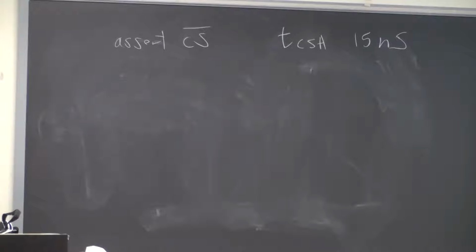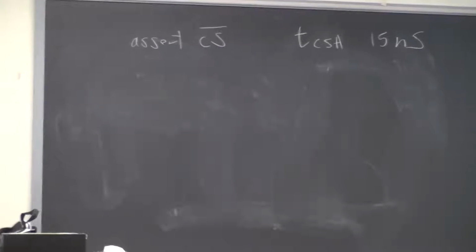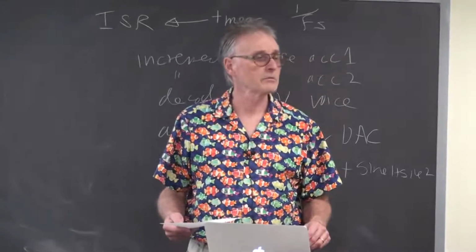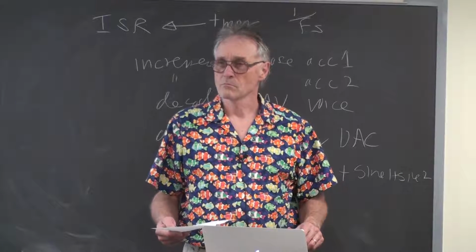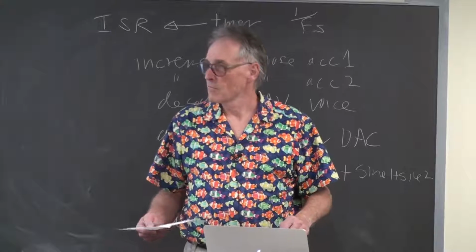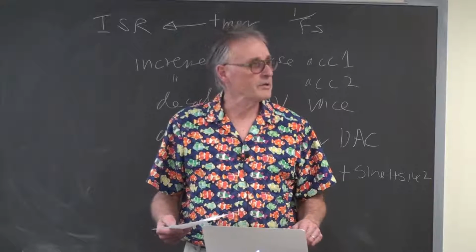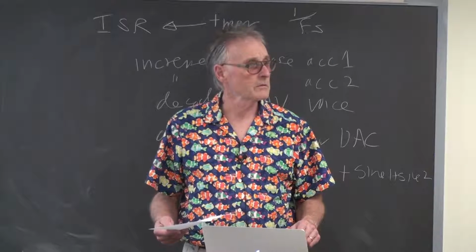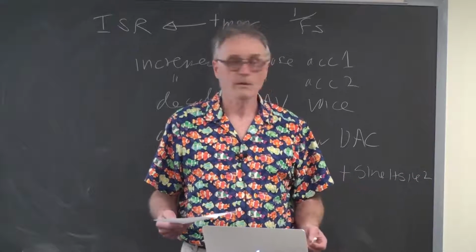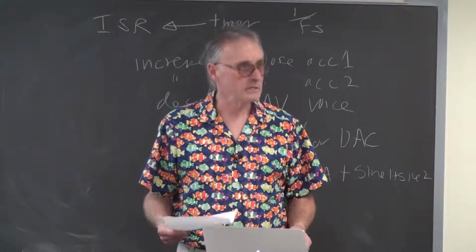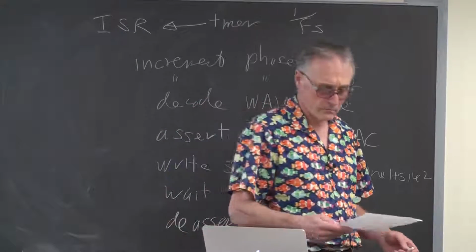So, can I do it on the next cycle? Yes or no? What's the cycle time of the CPU at 40 megahertz? 25 nanoseconds, right? So the answer is yes. You can do it on the next cycle.